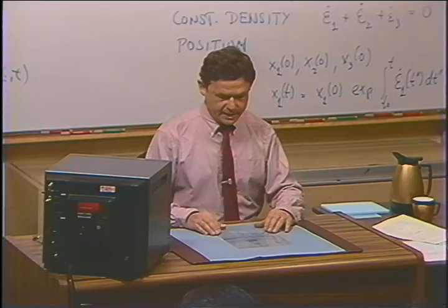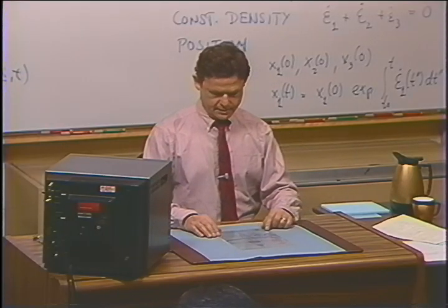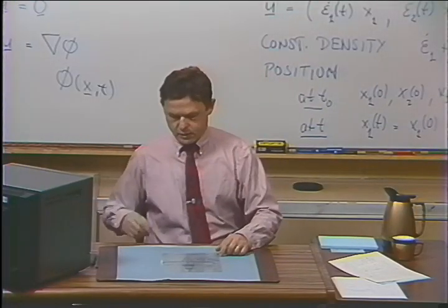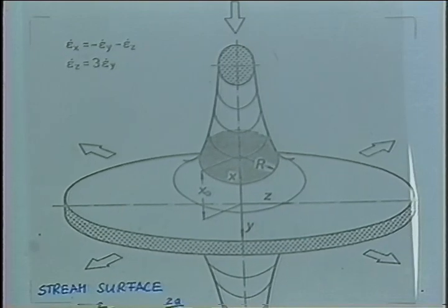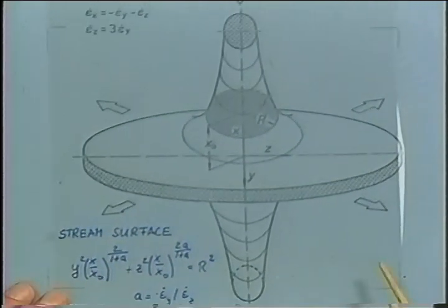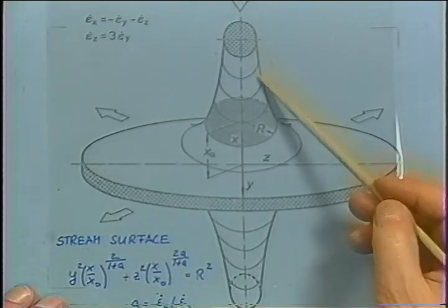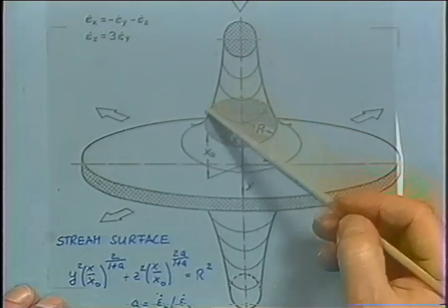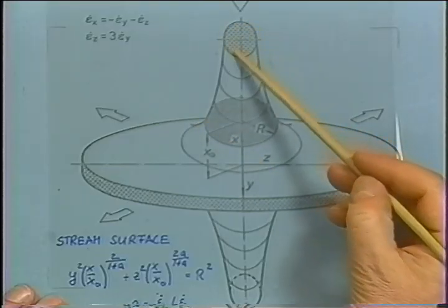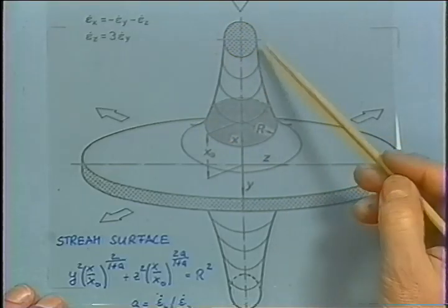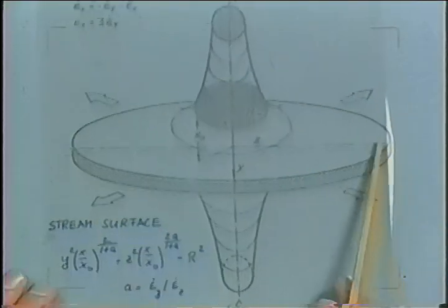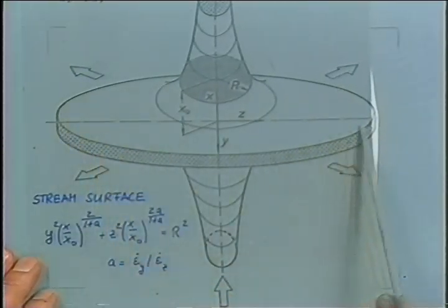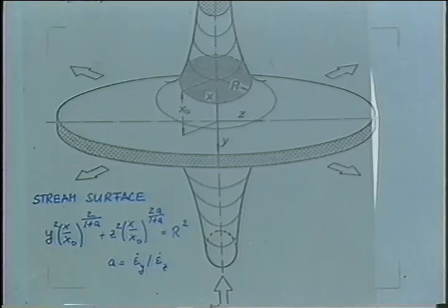The motion is given by a flow field, which I have here. If you use the figure here, we can define a stream surface which is given by material elements moving along a path like this. Initially, we would take material elements sitting on an ellipse like this, and as all those material elements move down in time, they would describe a circle, and sometime later, they would describe an ellipse stretched in the other direction. That's the most general format of the kinematics.